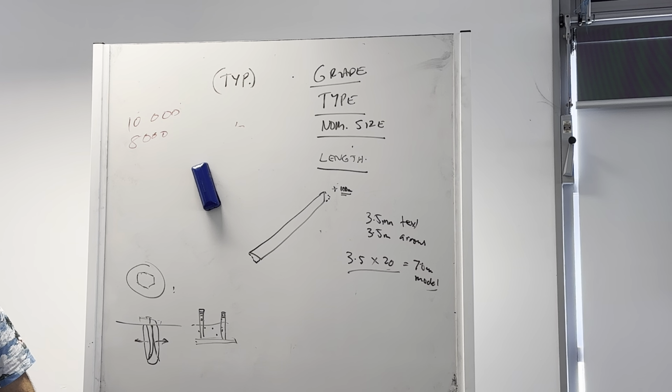It's handy to know. And a lot of companies don't draw in model space, they do their text in layout space, and you can link dimensions to a viewport. It gets pretty confusing, but you can do it, and that's quite a good way of getting around the whole calculation thing.